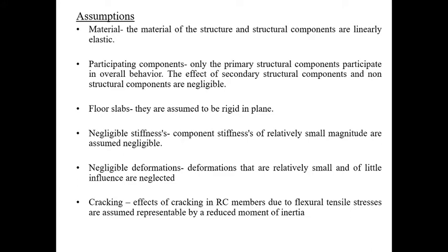So the first assumption we make depends on the materials. The material of the structure and the different structural components are considered to be linearly elastic. This is the first assumption we make. Now this assumption will allow superposition, meaning we can superimpose the actions and deflections here, and hence we can use a linear method of analysis.